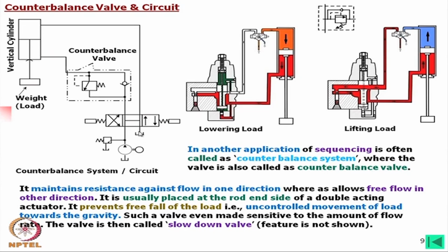Now, again we do not need a very fast response here. We can slowly lift the load and lower the load. The main purpose is to handle this load, not very fast operations. So, we can go for an open center to save energy, right. Now, we think of lowering the load, because that is the main purpose. While we are lowering the load, we allow this to go to tank, which means we will go to the left hand side.